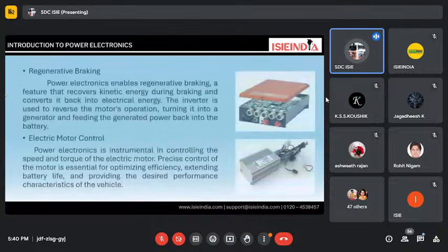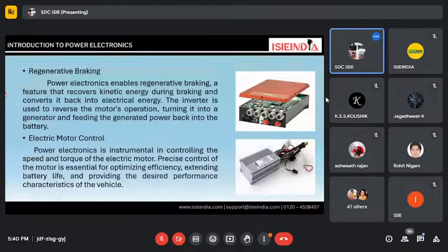Along with that, when we talk about regenerative braking, it's a very crucial topic. While the vehicle is running and we apply the brakes, we create energy. At that point, we need a place where we can store the charge. We can directly give that energy to the battery pack, or it can be stored somewhere else. For that, the regenerative braking components, MCU, and VCU have different components, and they have a super capacitor in them.